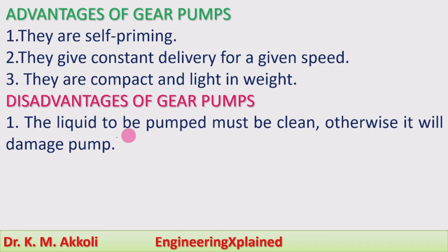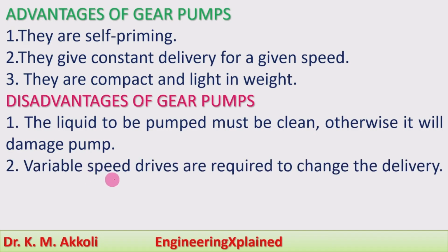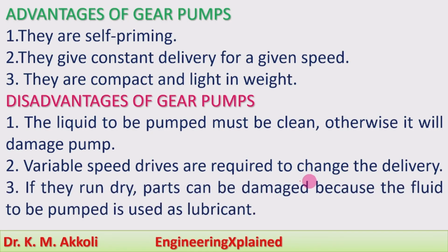Disadvantages of the gear pumps: the liquid to be pumped must be clean, otherwise it will damage the pump. Variable speed drives are required to change the delivery. At a constant speed, a fixed quantity of fluid is delivered. If a variable flow rate is required, we have to change the speed of operation of the pump itself.